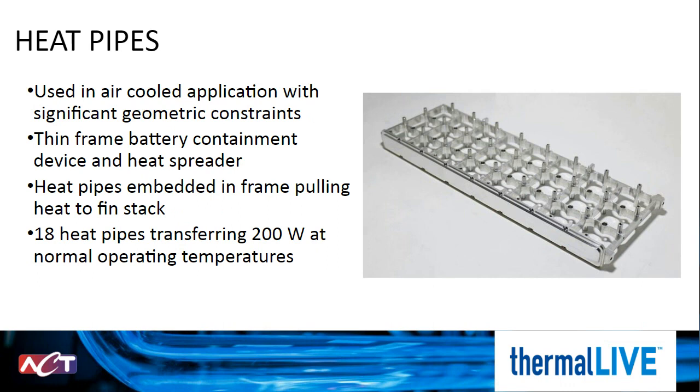As we said in the beginning of this presentation, a heat pipe can be used to isothermalize several heat-generating components. A battery cell pack has rows of uniform cells with energy conversion losses in the form of heat. Battery efficiency is based on the performance of its weakest cell. If one cell is experiencing more thermal loss, it'll degrade faster than the rest and will reduce the overall efficiency of the battery. But by spreading the heat and pulling away from the poor performer, you're able to increase the battery life while still having that weak cell.